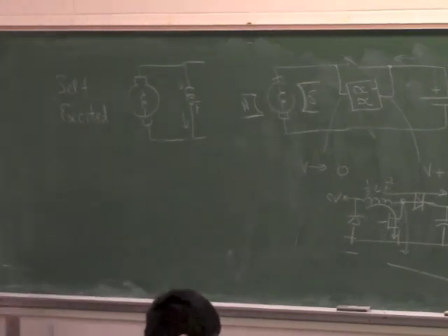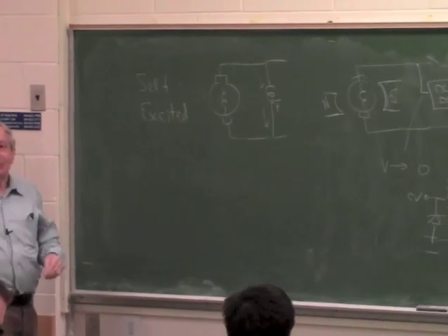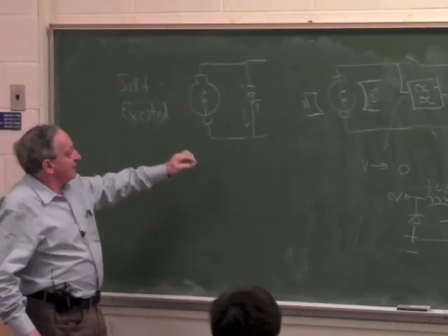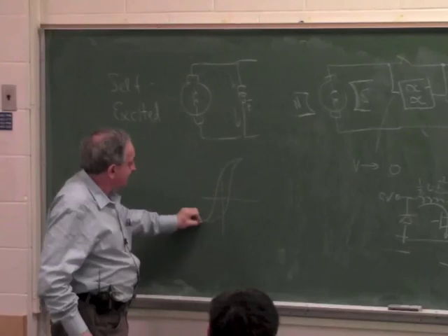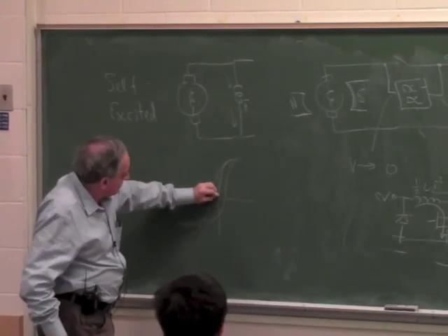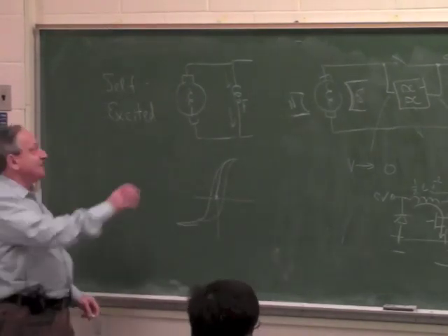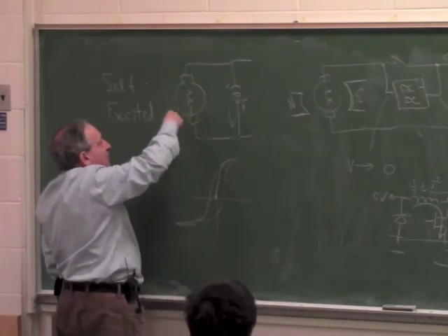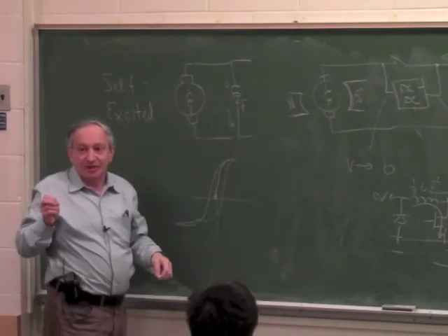Okay, good. Now, so it's very easy to understand. Now, when you talk about synchronous motors... Could you repeat the last part? Yes, because in every piece of steel, there is some residual magnetism. This is the hysteresis loop, and when you shut off the power, it doesn't come back to zero. It comes back with some little residual magnetism. So although it has no permanent magnet, it has a bit of magnetism, so when you start turning the motor, there's a bit of voltage created here because of the residual magnetism.